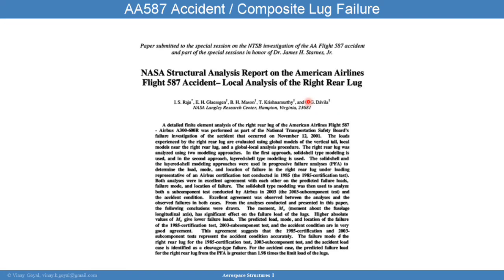They were able to reproduce, with excellent agreement, the failure modes and the location of failure using this advanced modeling. After they anchored the models with the 1985 test, they used the analysis to analyze the component level testing conducted by Airbus in 2003, later on as part of this investigation. They also found excellent agreement between the analysis and the observed failure modes.